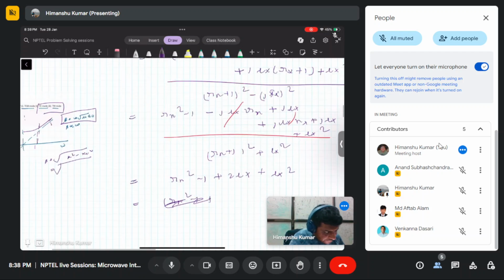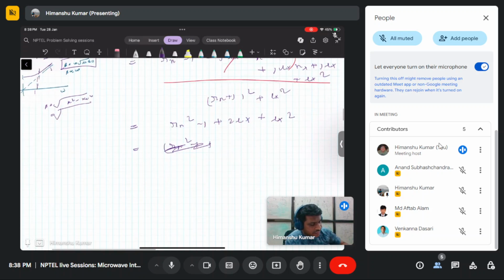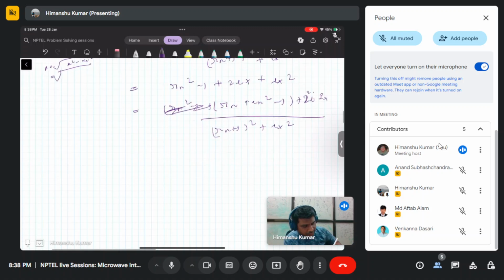The real part is rx square plus ix square minus 1, plus j times 2 times ix, divided by rx plus 1 whole square plus ix square, equals gamma r plus j times gamma i.